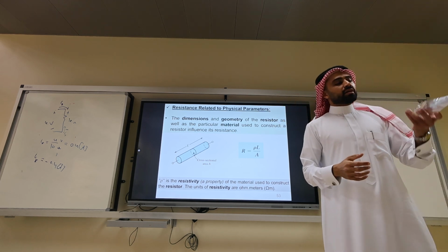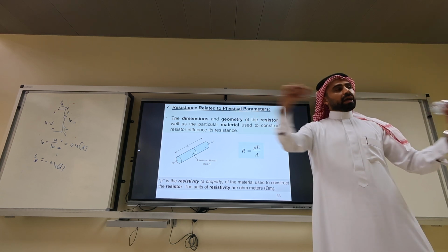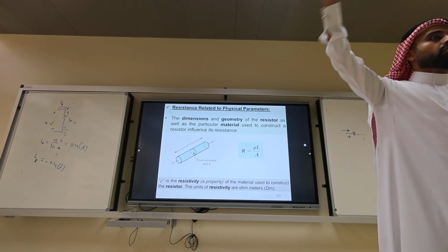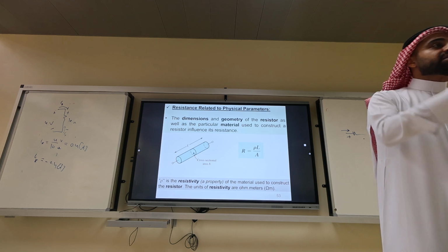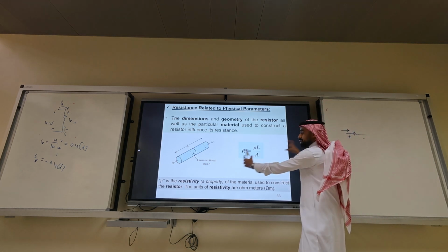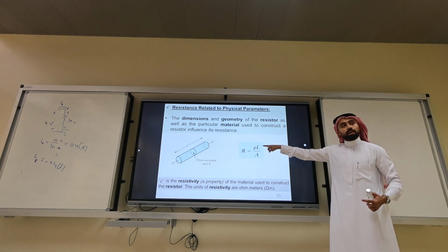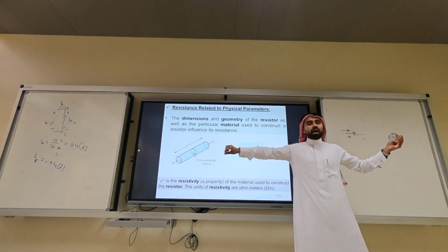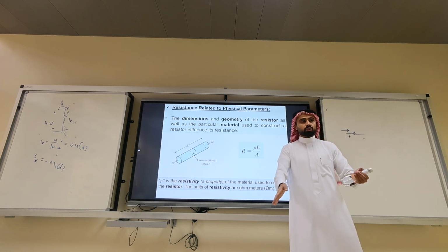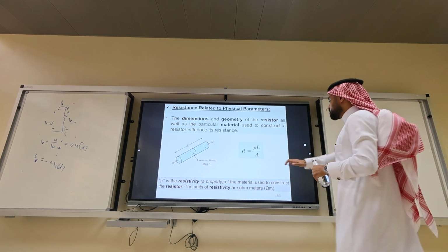In other words, الريزستيفيتي هي خاصية بالمادة والريزستنس هي خاصية بالكيبل حقك. يعني لو الكيبل حقك نحاس، كل كابل النحاس الريزستيفيتي حقتها واحدة ثابتة، بينما الريزستنس مختلفة حسب الديزاين. For example, if we have a wider cross-sectional area, you will have less resistance. If you have a longer cable, very long, you will have more resistance because more objects would resist the flow of electrons. Get it?